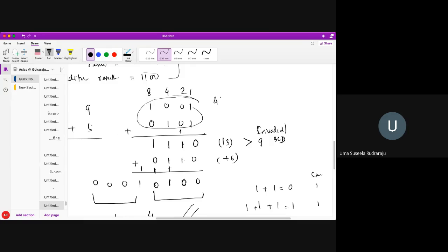Yes, a 4-bit adder can do this. We know that there is an IC called 74LS283 IC, which is a 4-bit adder IC. So I can take a 4-bit adder IC and perform the addition operation, whatever the sum comes here, S0, S1, S2, S3.